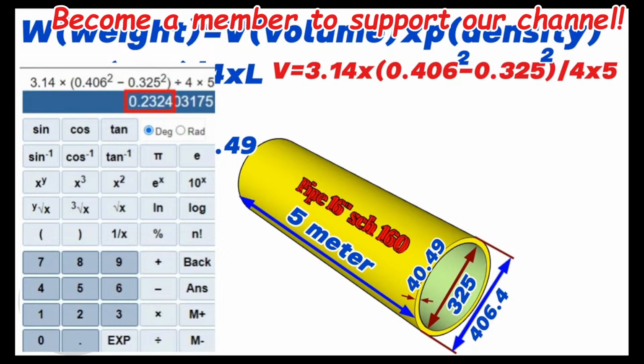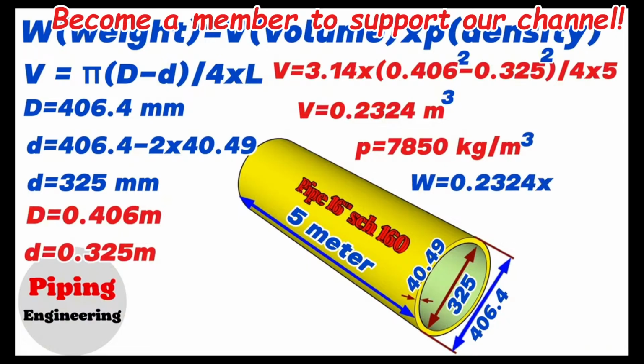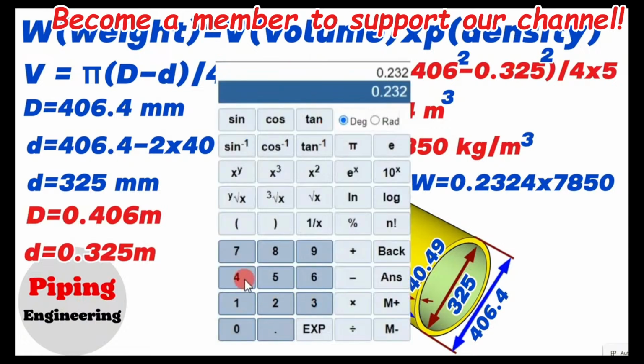So, we calculated and found that the volume of the 16-inch pipe in our example will be equal to 0.2324 cubic meters. We already knew iron steel density is 7,850 kg/cubic meter. Now let's write this information in the weight calculation formula. Weight equals volume, 0.2324 cubic meters, multiplied by the density of the material, 7,850 kg/cubic meter, of the pipe. Using the calculator, we find that 0.2324 multiplied by 7,850 will be equal to 1824.